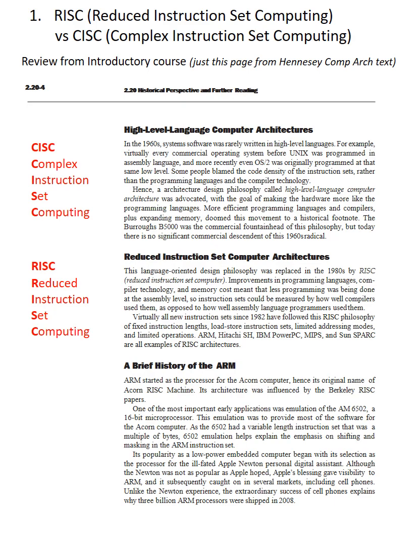It's faster to have fixed fields in your instructions for execution, for decoding. The machine can begin to immediately go fetch operand as soon as it sees the opcode and knows right where the opcode is going to be. It's a fixed set of bits. In IBM, we had a big complex machine with a complex instruction set, so we had actually some bits that would say, go get the rest of the opcode somewhere else. It was that big because we got up to 1,400 instructions when I was there.